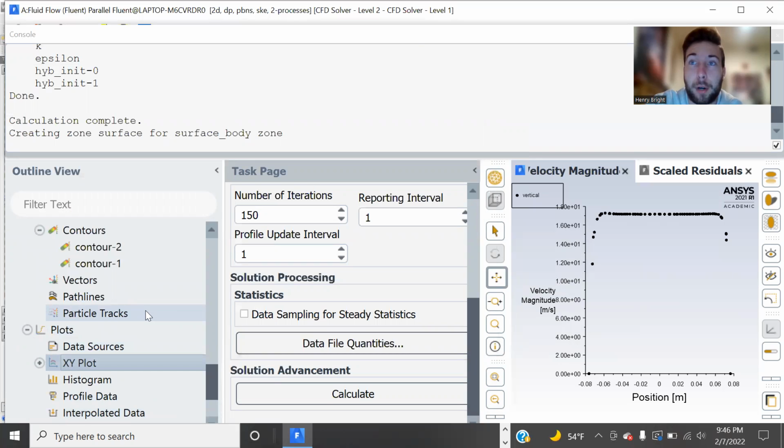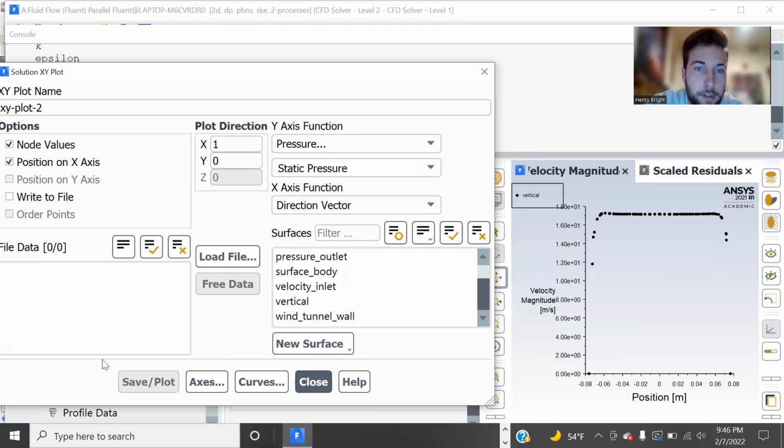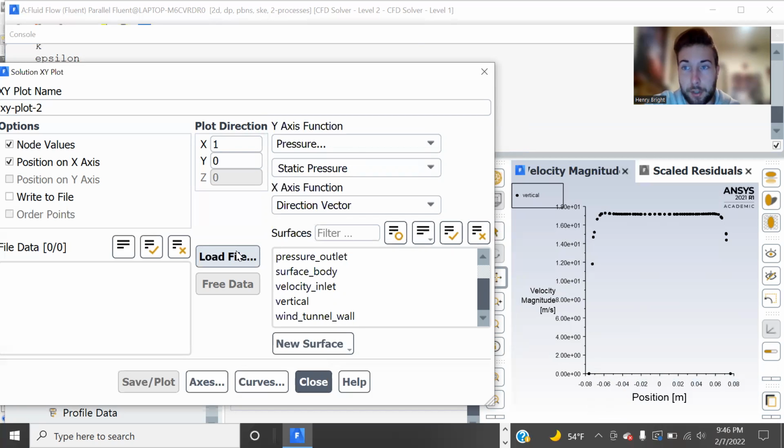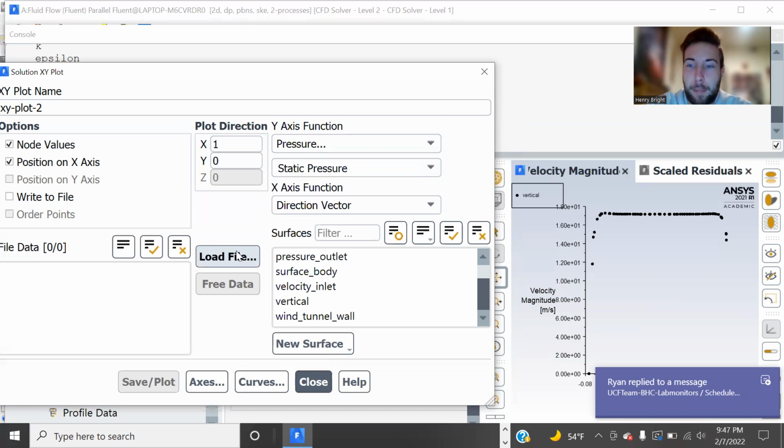The only other thing is the calibration. So what I did for the calibration is we need first the pressure change over the contraction chamber. So I ended up finding the lengths, I don't have them off the top of my head, of the x coordinates of where the contraction chamber started to where it ended. And I did a center line, a line through the center at y equals 0, to get the measurements of static pressure there so that I could then just write it to a file, get the maximum, get the minimum, subtract, and there I have that pressure change.